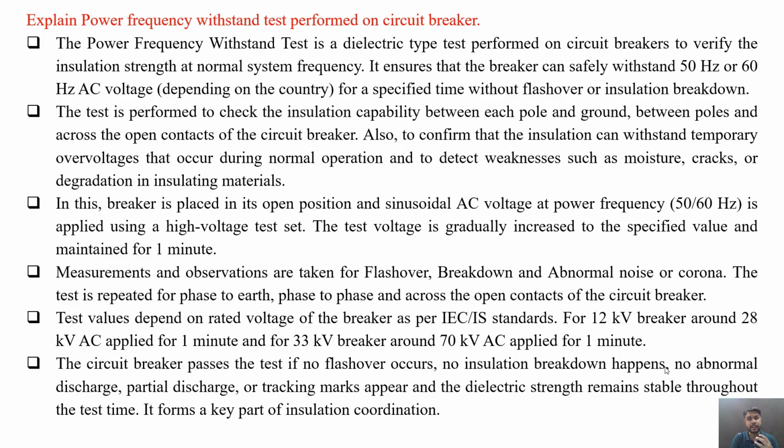It ensures that the breaker can safely withstand 50 Hz or 60 Hz AC voltage, depending upon the country, for a specified time without flashover or insulation breakdown. The test is performed to check the insulation capability between each pole and ground, between poles, and across the open contacts of the circuit breaker.